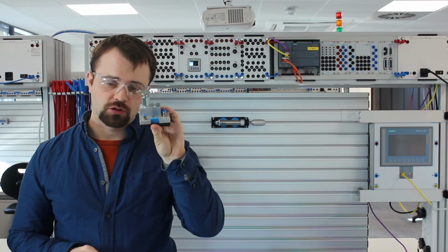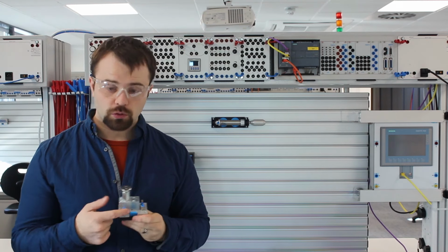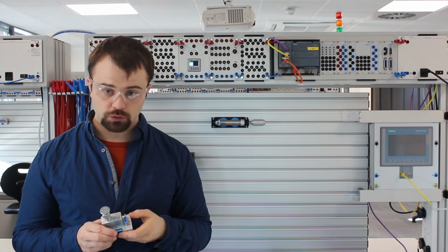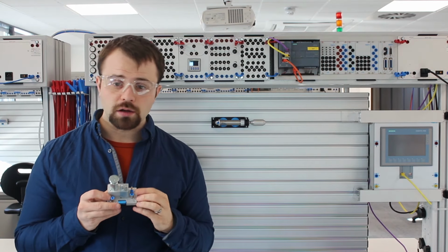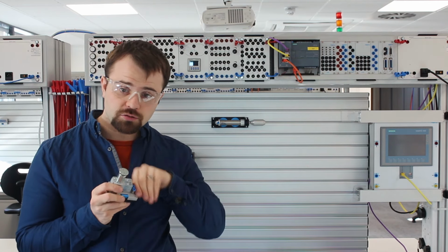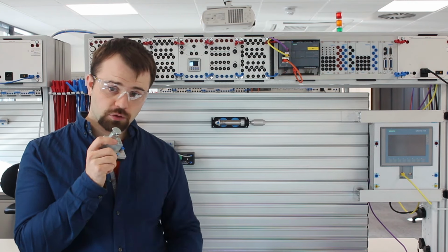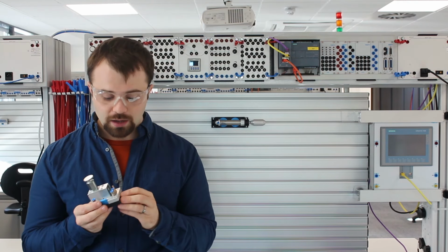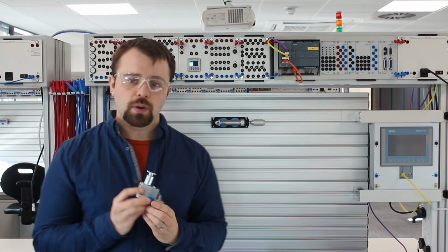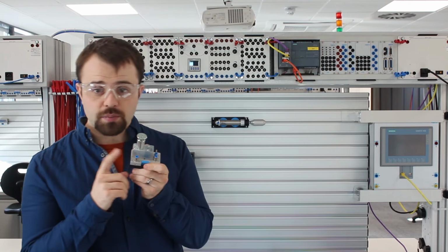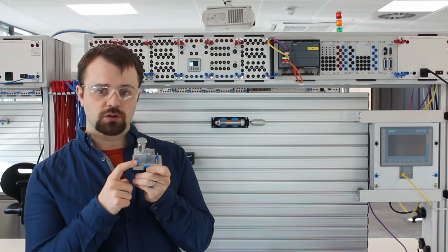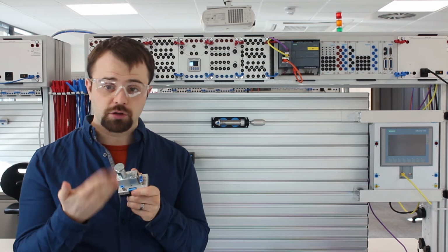So the second and final component is this. It's a pressure switch. It has 3 ports on it and an exhaust. So we have a 1 and a 2. This is the air that is going through this switch, because this is just a switch. So the air is going through the switch. And we have 1, 2, again, to connect 1 and 2. And this is where we're going to be monitoring our pressure. So whatever the pressure is going into 1, 2 is what causes the switch to trigger or not.